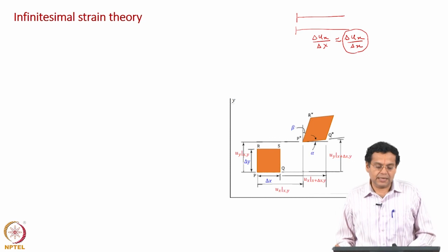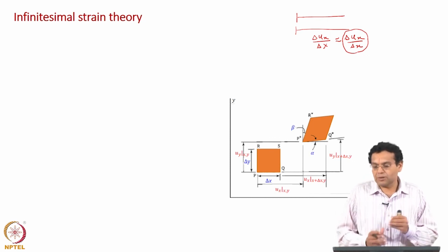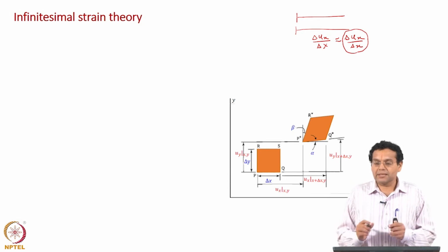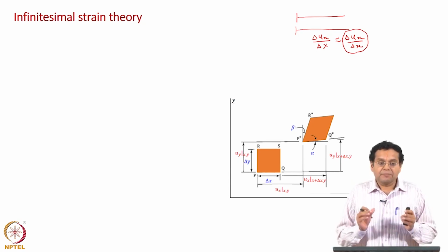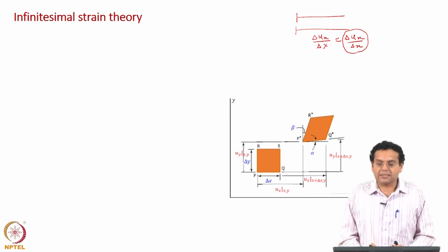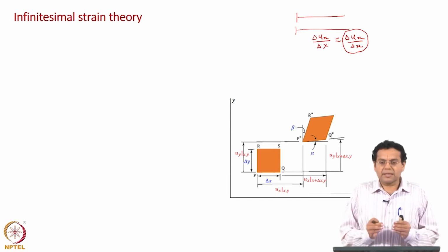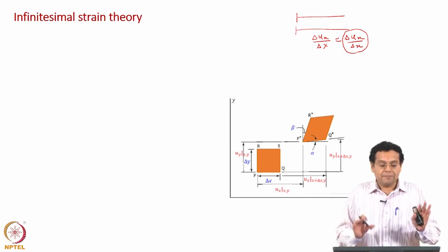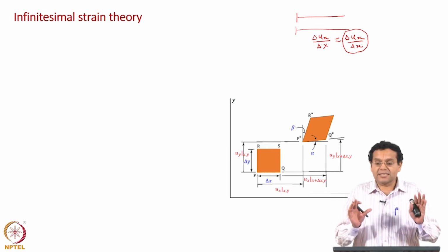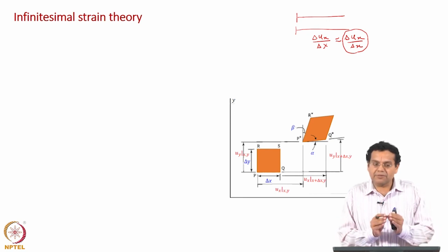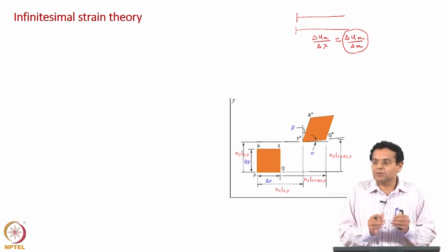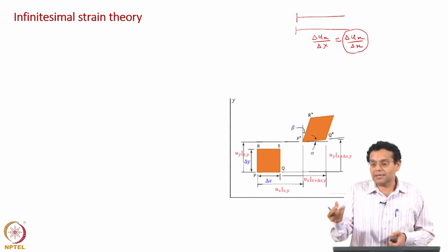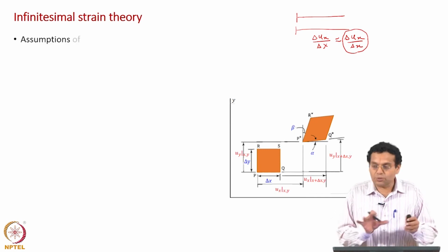Later on you will see that when you go to fluid mechanics, we are going to carry over all that. It is not an assumption in the case of fluid mechanics. Okay? It is an assumption in the case of solid mechanics. And remember, we are discussing solid mechanics under that assumption, because we have come to solid mechanics to take some concepts to fluid mechanics. So, we are not discussing the general finite strain theory. We are only discussing a part of it, which is infinitesimal strain theory, so that I can take over these concepts to fluid mechanics, and that is not an assumption there. You will understand that later on. Okay? So, that is the scope of this discussion.